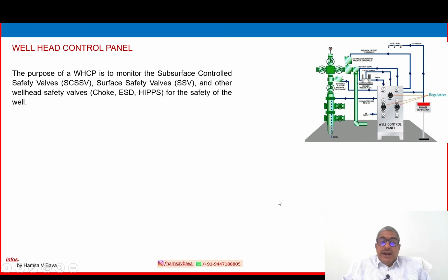The purpose of a wellhead control panel is to monitor the subsurface controlled safety valve. The important word is monitor. Monitor and control, so it is monitoring continuously. So the purpose of the wellhead control panel is to monitor the subsurface controlled safety valve, surface safety valve and other wellhead safety valves like choke, ESD and HIPS, high integrity pressure protection system, etc. for the safety of the well. So the entire safety of the well is monitored by the wellhead control panel.